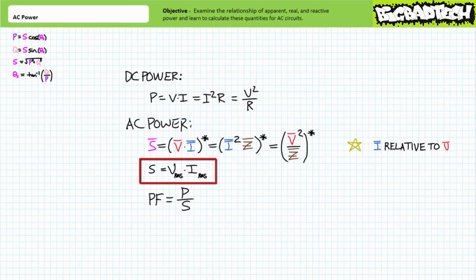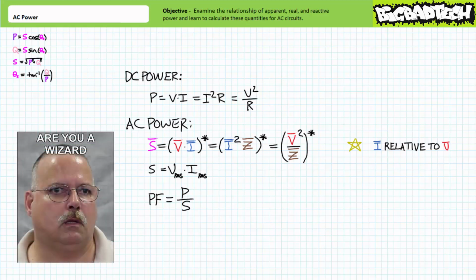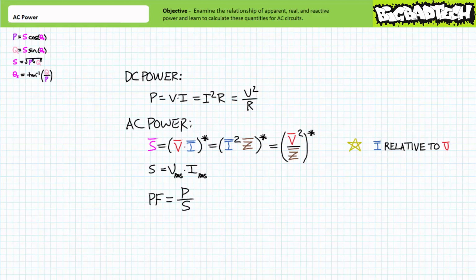To calculate apparent power magnitude using the old school method, take the effective or RMS voltage and multiply it times the effective or RMS current. S equals V times I. Easy. You note that apparent power magnitude obtained using this technique is the exact same magnitude as that obtained using the complex number representation. It's just that there's no angle associated with it. But don't you dare point this out to anybody using the old school methods, because all you'll get in reply is a blank, uncomprehending stare. The old school methods don't use angles and don't use complex numbers.